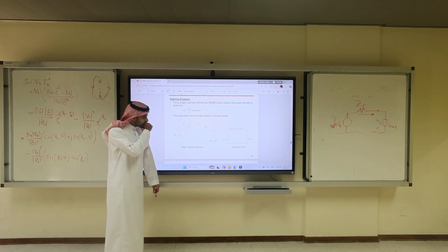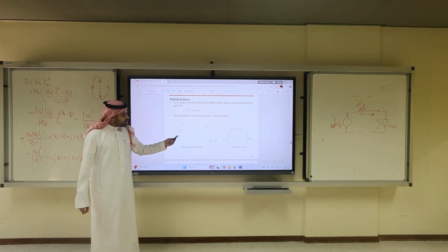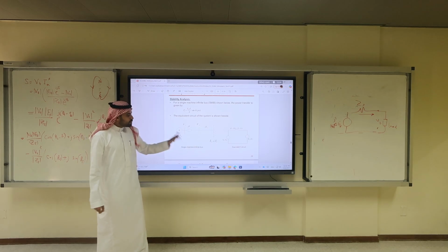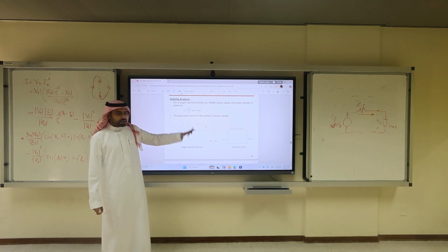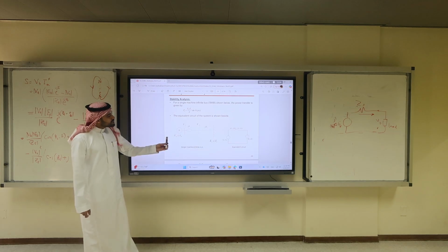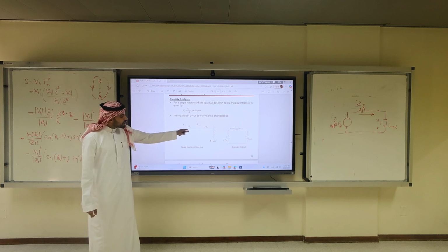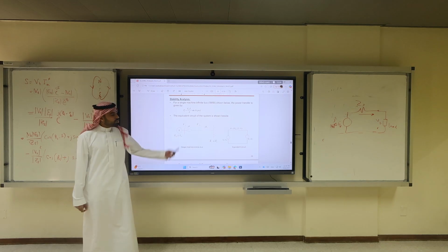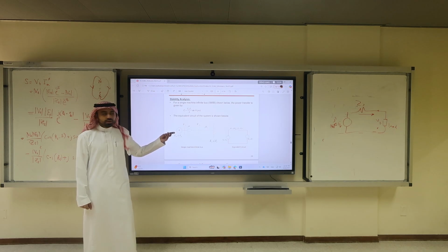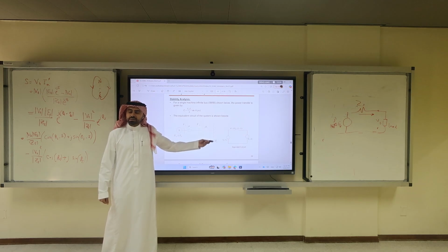It is the reference. So it turned out delta, which is delta G minus delta S, if delta of S is 0, the difference is delta G, so delta G would equal delta. Then you would notice that you are impacted by X of the generator, and X of the transformer, and X of the line. So now power engineers, do they have to change X of the generator to control the power if they don't want to change the delta? No. They can change X of transformer, they can change X of the line. Which one is easier? It's the lines.